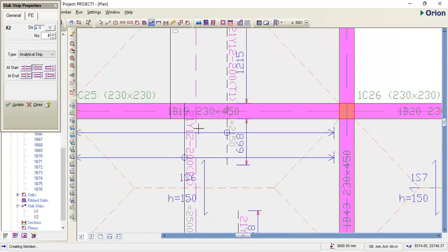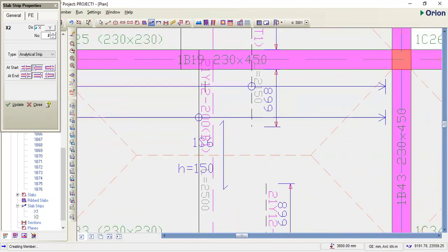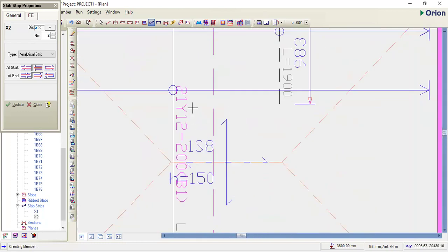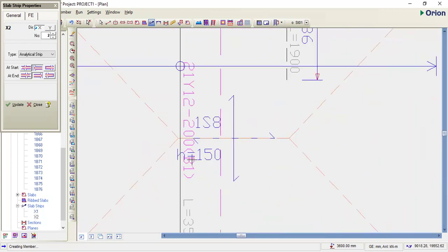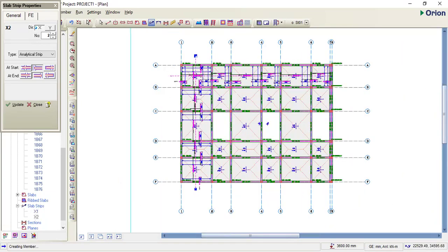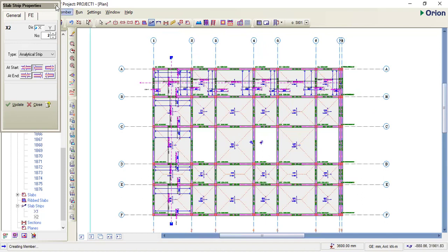That is 250 because we did not set. But now that we have set it, each of the panel slab reinforcement details is showing Y12 at spacing of 200 both top and bottom. That is what it means. And that is what the design specifies. All right. So you can close it.